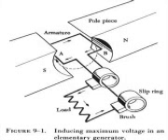Terminal A receives current from the negative generator brush through the shunt field winding. This current passes through the voltage regulator and back to the armature through the positive brush. Load current, which leaves the armature through the negative brushes, comes out of the E lead and passes through the load before returning to the armature through the positive brushes. Regulation of generator voltage minimizes field distortion. Thus, the interpole tends to keep the neutral plane in the same position for all loads on the generator. Therefore, field distortion is reduced by the interpoles, and the efficiency, output, and service life of the brushes are improved.